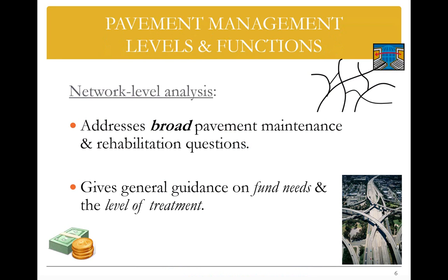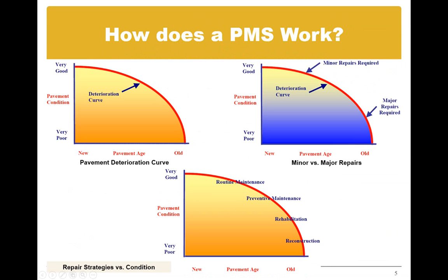So the maintenance activities are gonna be related to the pavement condition. For example, if I have a really good pavement condition, then this is gonna trigger very minor repairs. For example, like what we talked about in chapter 1, we may be able to do a minimal amount of seal coats or fog seal coats, or all the way to maybe chip seal.